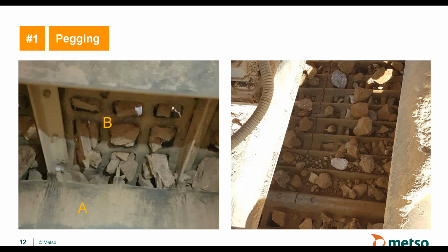So in these cases, there is really only one solution to work with if you want to maintain the exact same screen body, and that is to work with the layout of openings and to move them away from these areas and blank out the areas which are in danger, let's say, from this. So the openings on top of the crossbeam should effectively be blank to avoid this phenomenon.